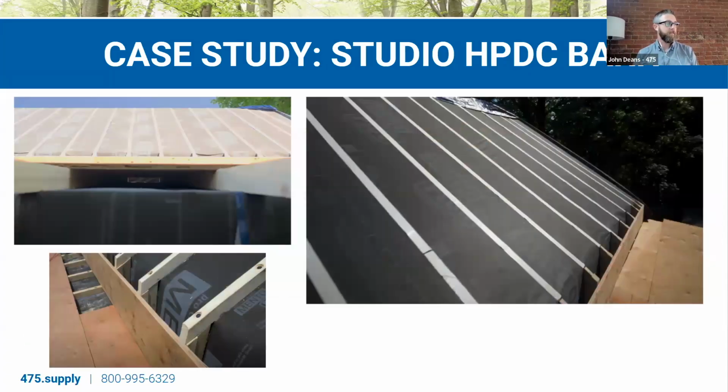And then this is a look at that vent channel. So this is how they had to turn up the wall. And their battens on the roof are 2-inch. So they just rip down 2x for that. And then they're a little bit thicker on the wall. And that may have come from consulting and sort of doing some modeling to see what they needed for maximum airflow there. So that was a cool little tricky detail.